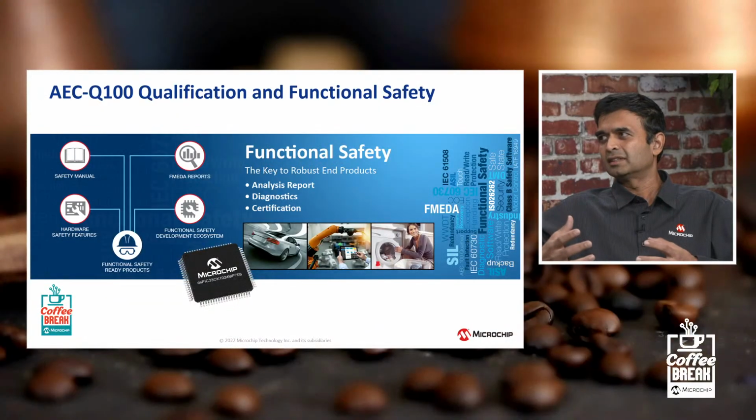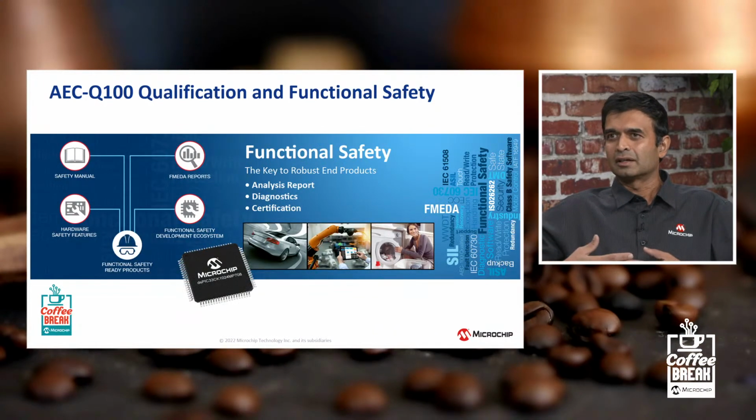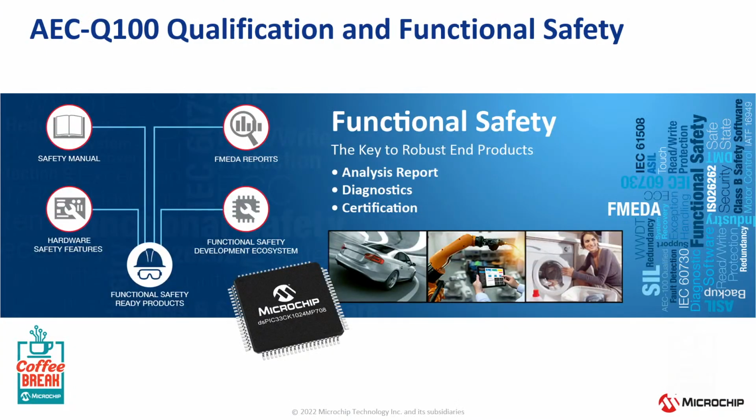Sure, yeah. So AEC Q100 qualification is mandatory really for our controllers for automotive chargers. And really Microchip has a lot of expertise with AEC Q100 qualifications. And in fact, some of our controllers are qualified up to level of grade 1 and even grade 0. So we have really a lot of expertise with Q100 qualification. And even some of our other components on our system, on our reference design, are all Q100 qualified, of course.